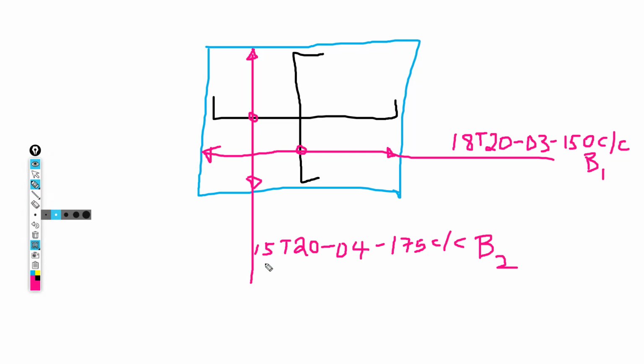that is an ID which is given to reinforcement, which is changing in a particular confinement zone. Okay, so when you look at this bar here, it is going to have a different length compared to this bar, isn't it? So whenever you have a change of length, a change of bar type, if this is T16 and this is T20, those are different bar marks.